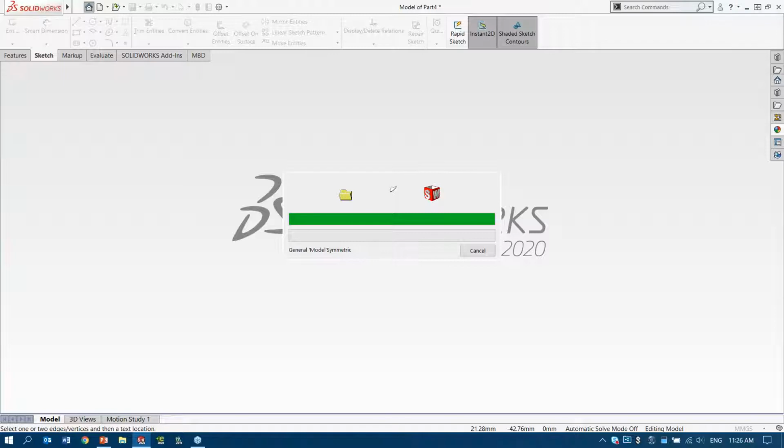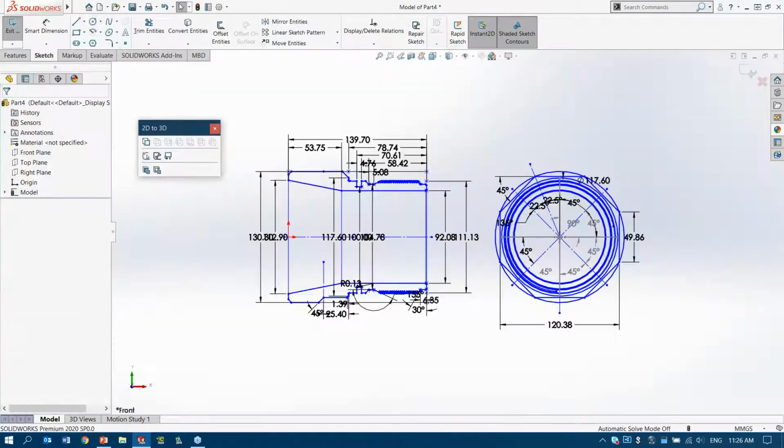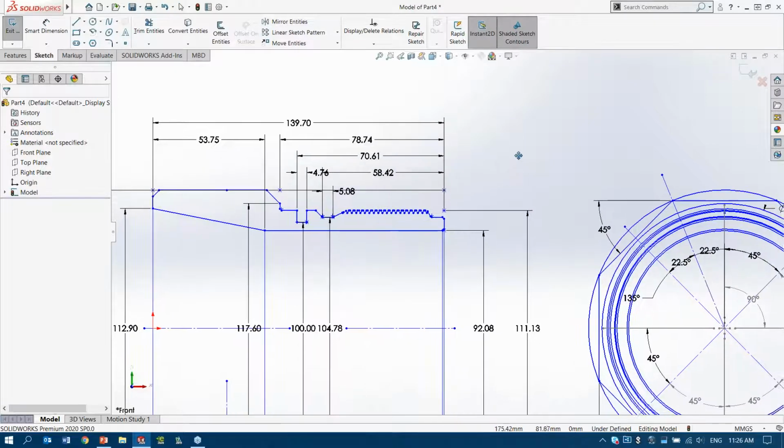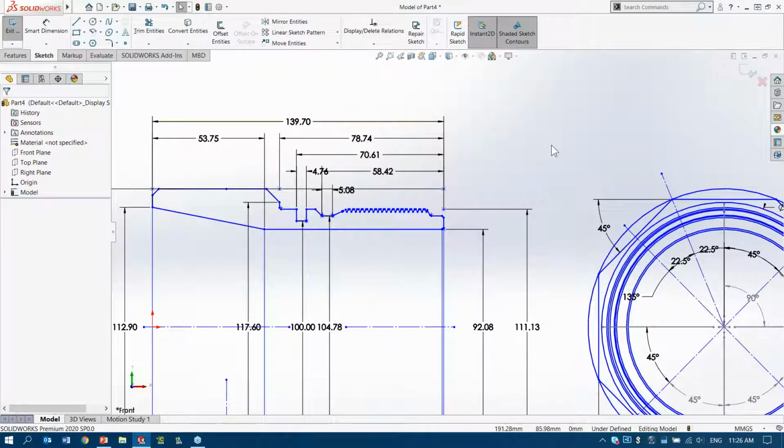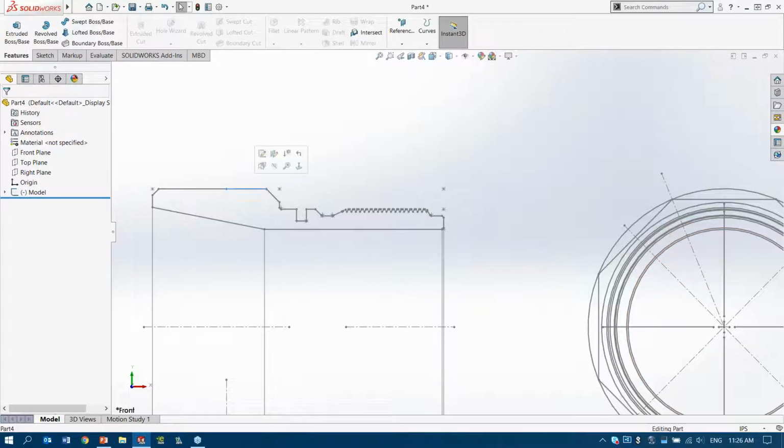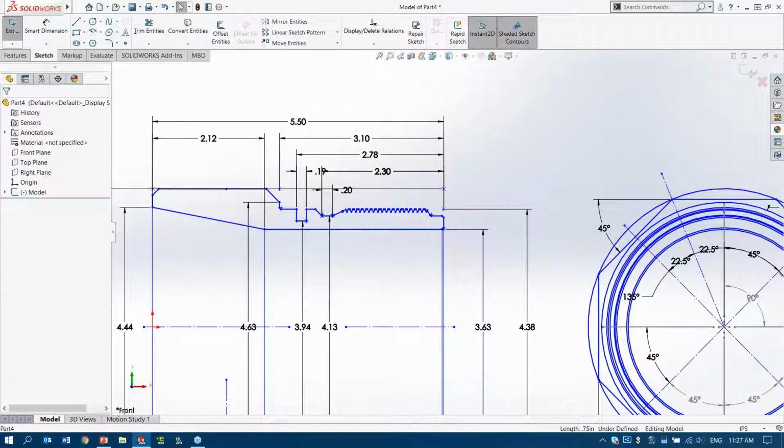And this is being imported now inside of SOLIDWORKS, but the entities are different from my first layout, where I simply used the layout as a reference and put stuff on top of it for positional information. This one here I want to change. Now you probably realize that the dimensions are off. That's simply because my SOLIDWORKS template is in millimeters. So let's put it back in inches. Doing that, you see very quickly that all my dimensions are in inches.